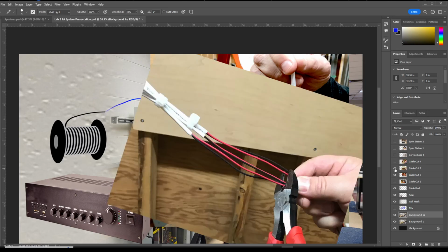Now after that, we're going to add that third wire and more or less equalize the jacketing. If it's just a little bit off, that's fine. But what's important is that after we have all those wires of equal length from that tie-off point, then now we can trim them to the same length. And again, do not shortchange yourself on the length of the wire.